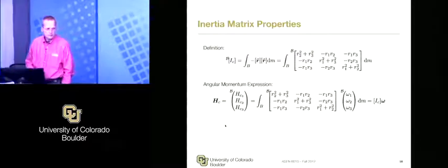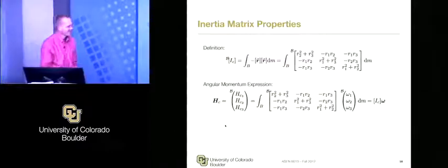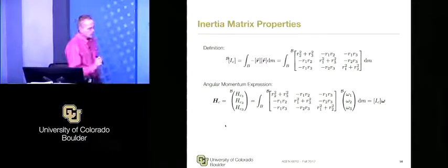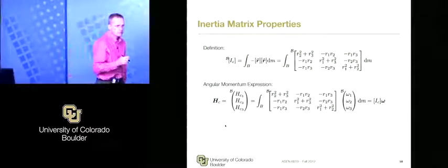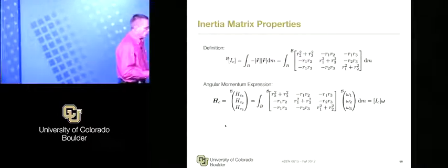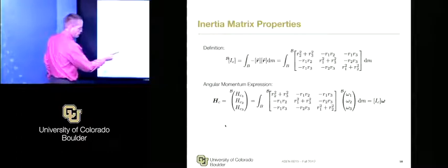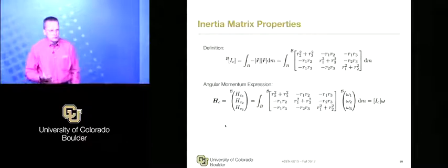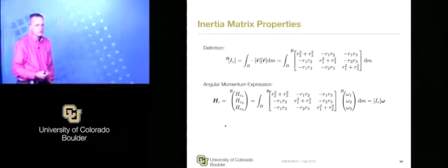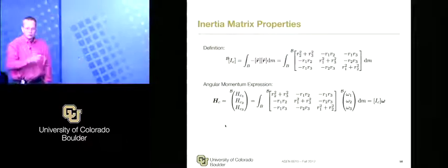H dot equal to L. What type of time derivative are we taking, Patrick? Inertial. And with respect to what frame are you taking vector components here? The body frame. So are the body frame components constant? No. So these can actually vary with time, even with no external torque.